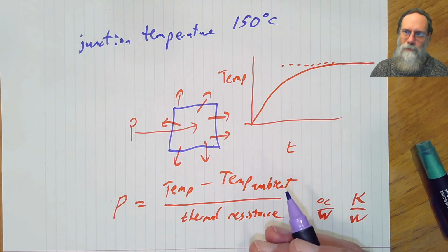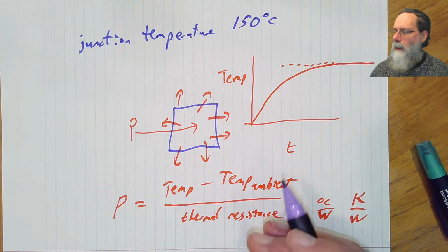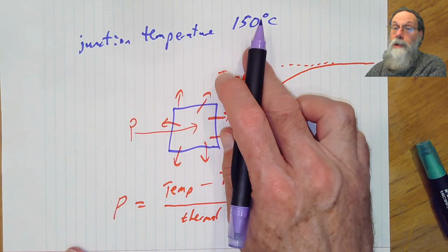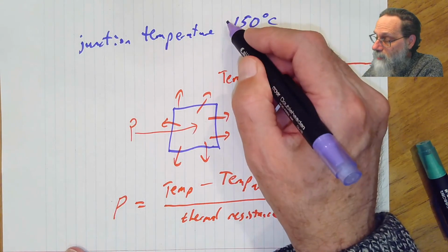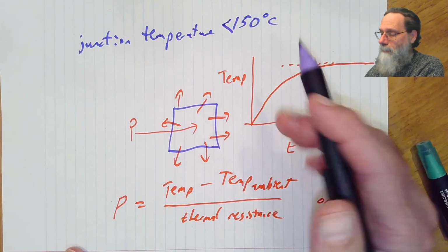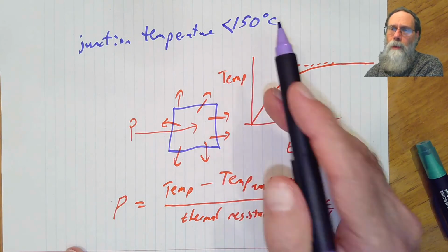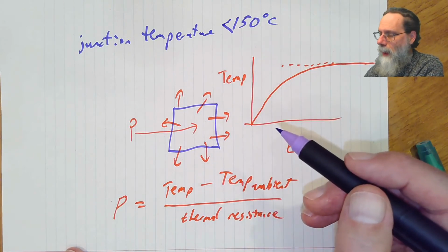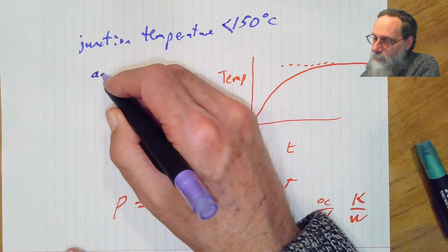We've got a transistor we're going to be switching some power with. We're worried about how hot does it get. Well, the junction temperature has got to stay less than that. So the junction temperature has got to stay less than 150 degrees C. And if you want to be safe, you generally stay a fair amount below the absolute maximum. Then we have, well, what's our ambient temperature?